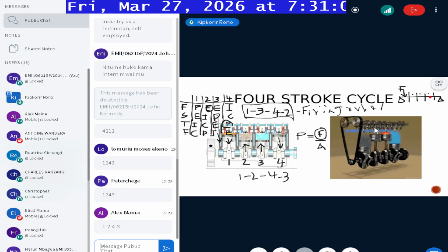The crankshaft can only withstand a certain amount of stress produced in a linear manner. It is supported here and here, so assume that it is simply supported, because the crankshaft is basically placed on 2 ends.